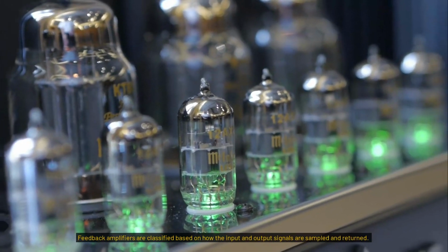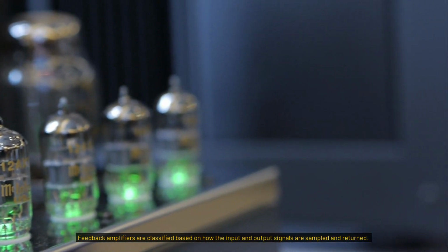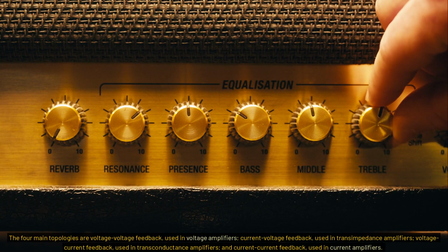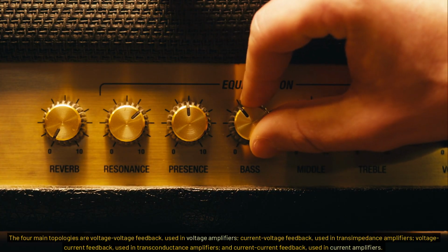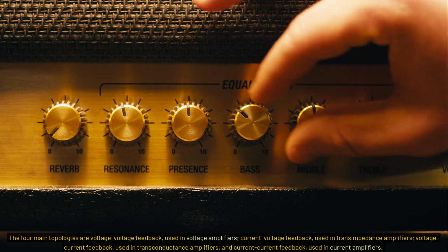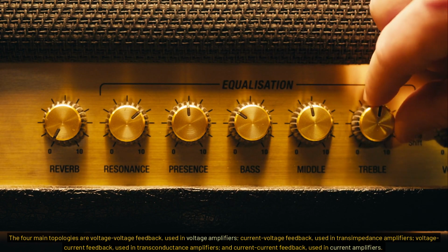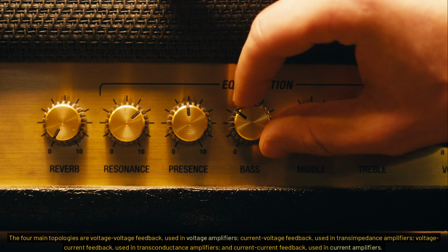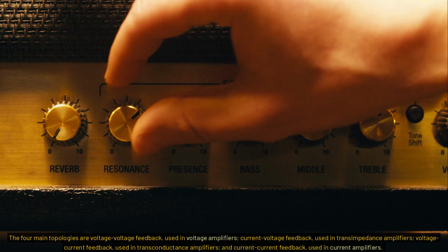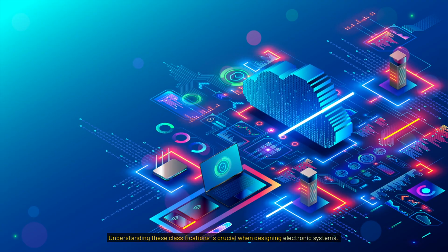Feedback amplifiers are classified based on how the input and output signals are sampled and returned. The four main topologies are voltage-voltage feedback, used in voltage amplifiers; current-voltage feedback, used in transimpedance amplifiers; voltage-current feedback, used in transconductance amplifiers; and current-current feedback, used in current amplifiers. Understanding these classifications is crucial when designing electronic systems.